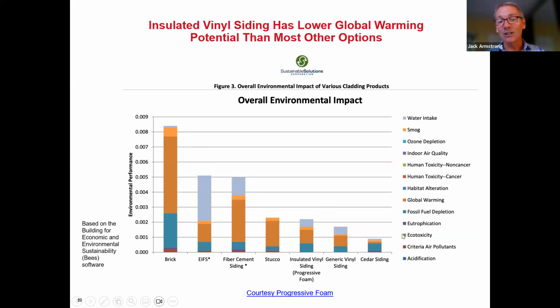Then what you have to consider is, well, what is the programming for my building? Do I have to worry about other things like maybe fire for siding or something like that? So clearly, a product like we just discussed, insulated vinyl siding, is not only a facade treatment finish, but it can help consider your continuous insulation and your regular insulation requirements for your building.